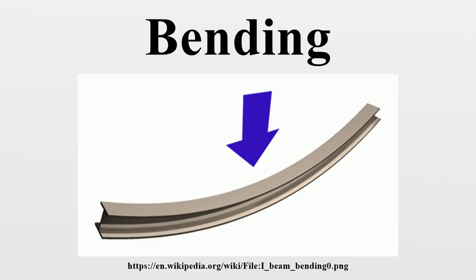The beam is initially straight with a cross-section that is constant throughout the beam length. The beam has an axis of symmetry in the plane of bending. The proportions of the beam are such that it would fail by bending rather than by crushing, wrinkling or sideways buckling. Cross-sections of the beam remain plane during bending. Compressive and tensile forces develop in the direction of the beam axis under bending loads. These forces induce stresses on the beam.